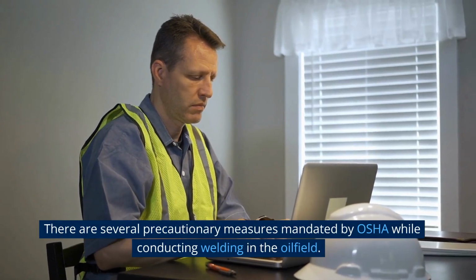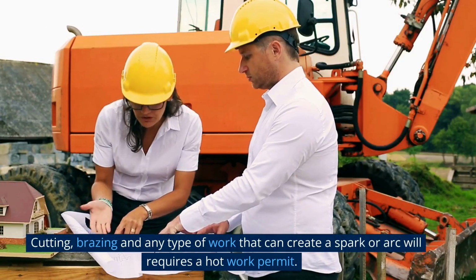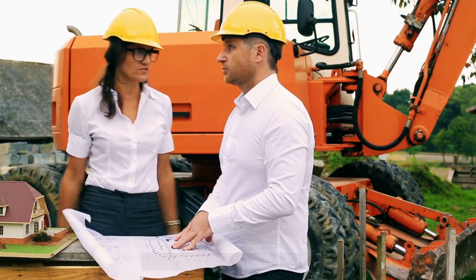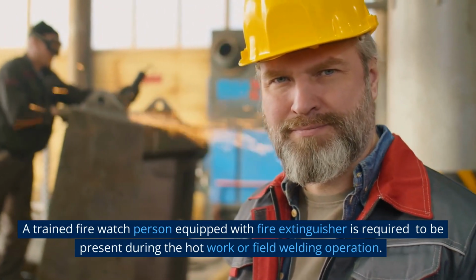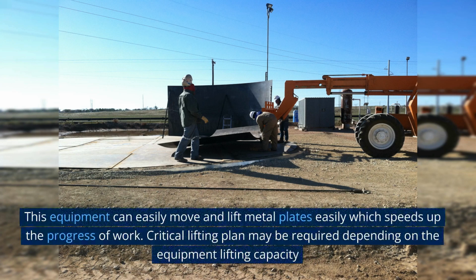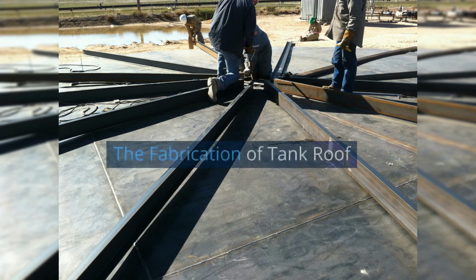There are several precautionary measures mandated by OSHA while conducting welding in the oil field. Cutting, brazing and any type of work that can create a spark or arc will require a hot work permit. A trained fire watch person equipped with a fire extinguisher is required to be present during the hot work or field welding operation. Heavy lifting equipment like a crane or a forklift with boom extender is necessary when constructing a tank. This equipment can easily move and lift metal plates, which speeds up the progress of work. A critical lifting plan may be required depending on the equipment lifting capacity.